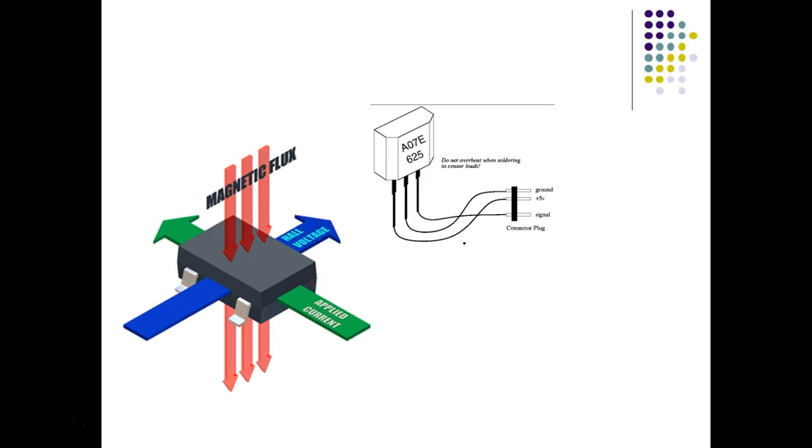Ground is earth ground. It means it's reference to earth ground, right? And then a common is not reference to earth ground. It's just the return conductor in a DC circuit, or it's your common conductor in an AC circuit. And we found out the other day that what our trainers call ground is not ground, it's a common. So this is one of the misused terms in the field. And just because you use ground, that's okay, but it's imperative that you understand the difference between a common and a ground.